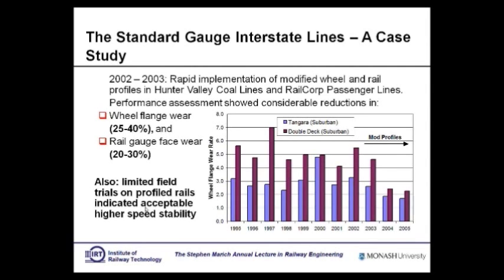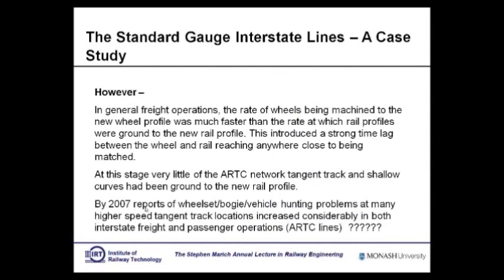It looks really good. At that time, we said, okay, fine, here it is, you have it. And we withdrew back to Melbourne, of course, the safety and the cocoon of Melbourne. As I said, you can implement a wheel profile very, very quickly. All you need to do is take your wheel set up to the lathe, and the lathe will go zip, zip. You've got a new wheel set, new wheel profile. So everyone started to implement the new wheel profile because they were very keen.